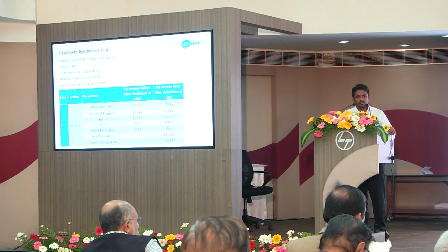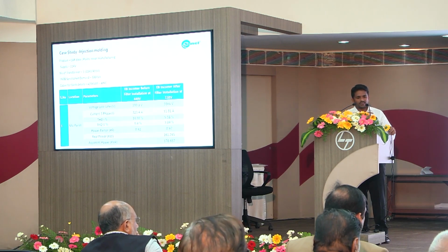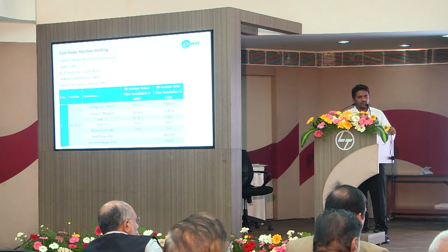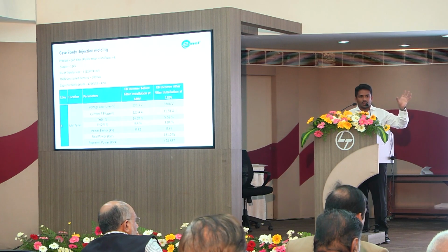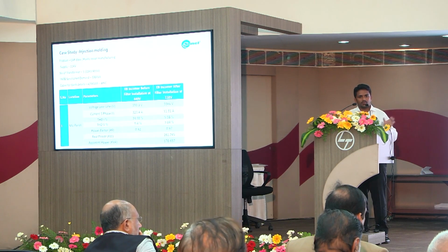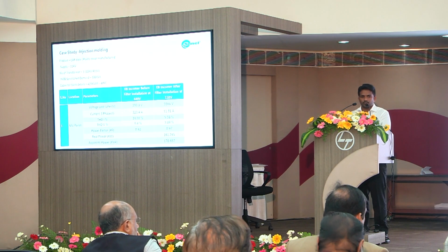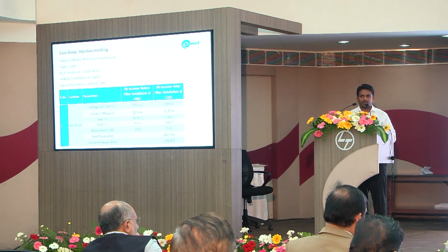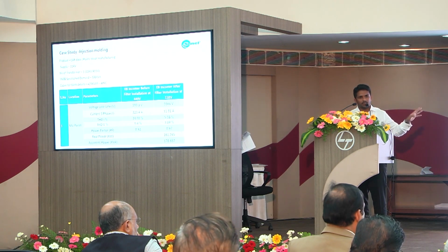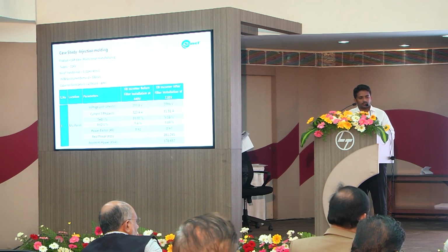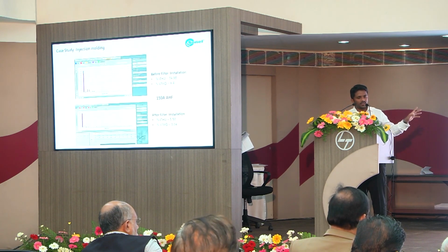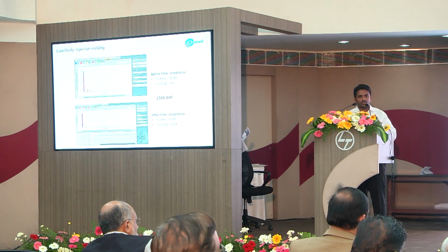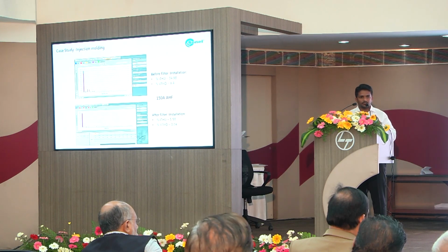So this is an injection molding plant. Please note that as a consultant or a company giving a solution, our solution will be on the LT side, the 440 volt side. But whether what we did is correct or not is tested and approved by the TNEB MRT department. So if I compare, for example, my harmonic percentage of 34.98, that is what I will be doing on the LT side.